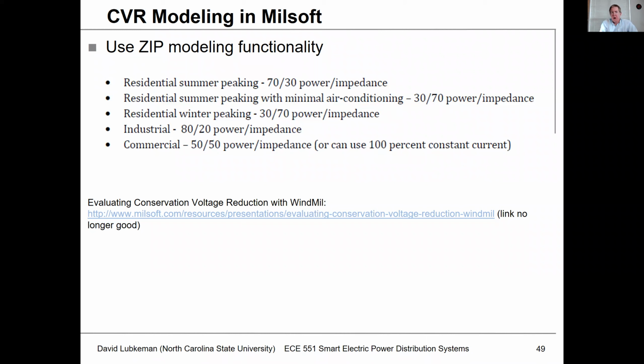So if we want to model CVR effect in Milsoft, then what we need to do is go in and change the coefficients on our load model. In Milsoft, we have the opportunity of using a mix of constant impedance, constant current, and constant power load.